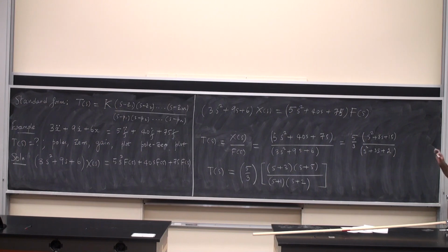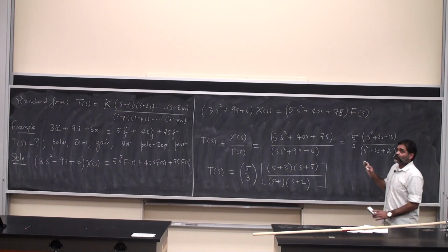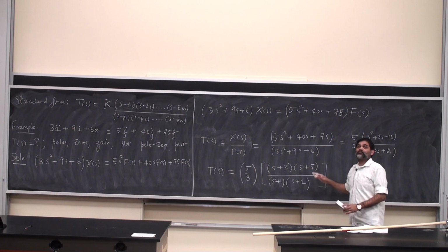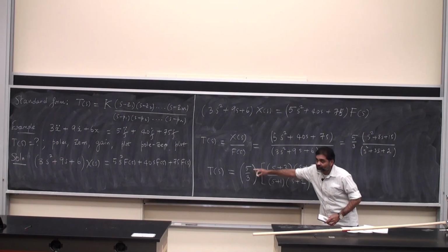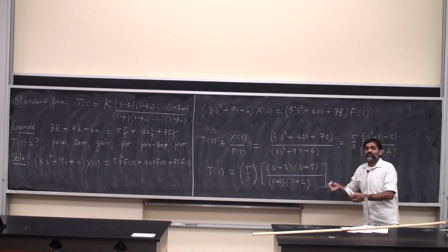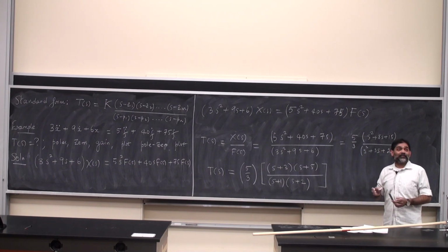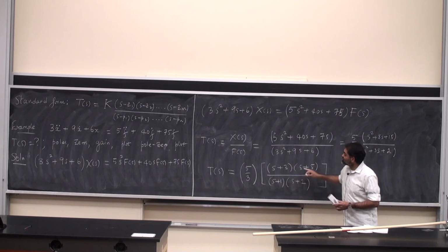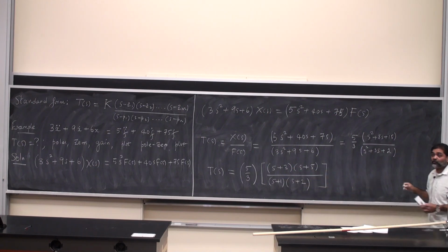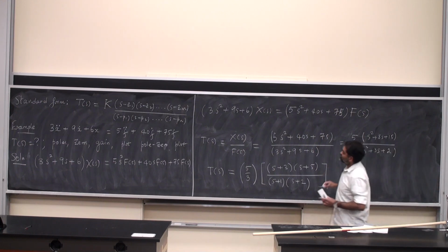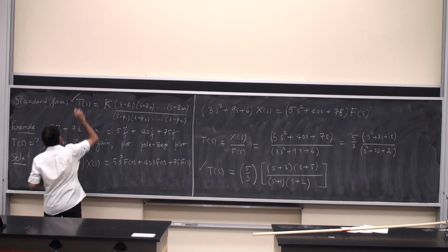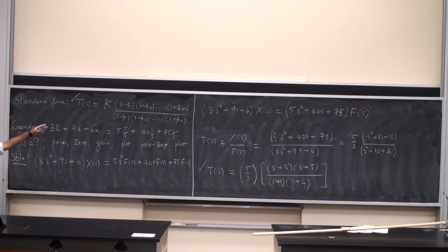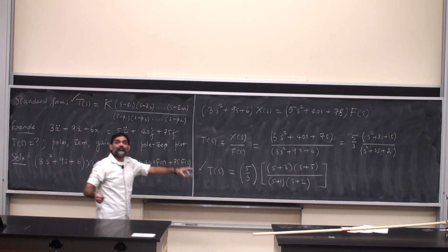So every time somebody gives you an equation of motion, you're going to do this multiple times when you do control system design. You always have to bring it to the standard form: the system gain, the meaning of which will become clearer later. I'm not interested in interpreting it for you today. The system zeros, the system poles. We know the system poles. They talk about stability. So by direct comparison between the standard form and this creature here, Z1 is minus 3, Z2 is minus 5.